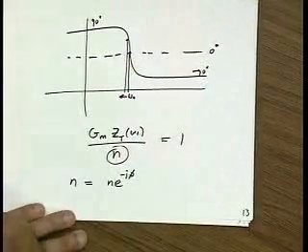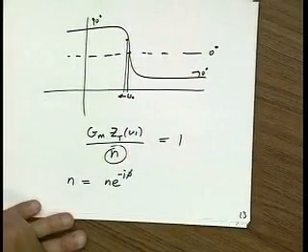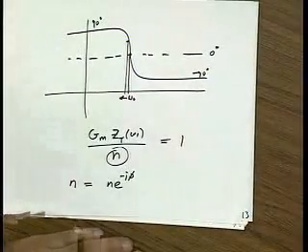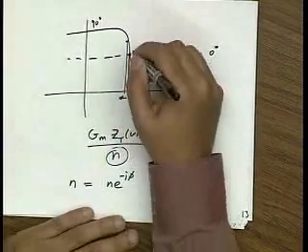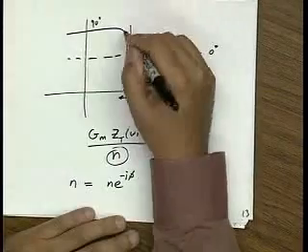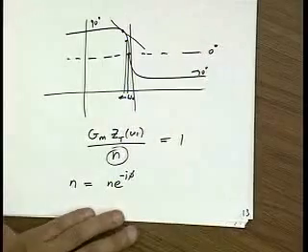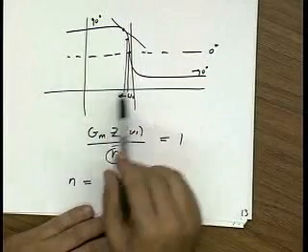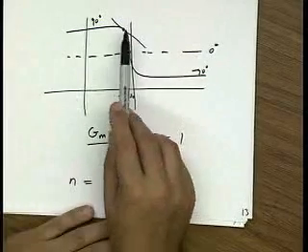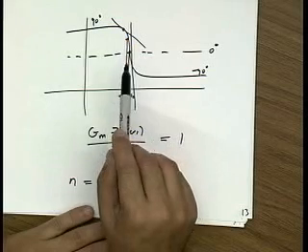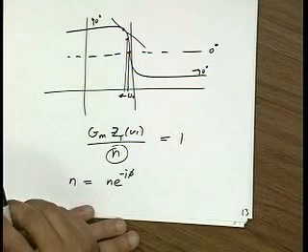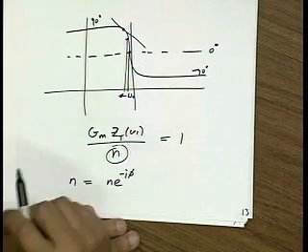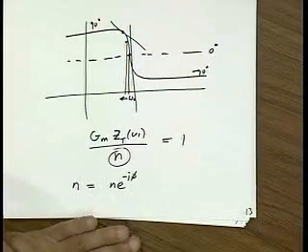So you might say, big deal. I'm not going to resonate exactly at omega naught. I can take that into account. Yeah, but you find out that the best point to oscillate is right here where the slope is maximum. You don't want to get to a point where this slope gets small, because the sensitivity of this circuit to phase noise is very much related to the slope. The higher the slope is, the less sensitive it is to noise on the phase. And so if you want the circuit to have good phase noise performance, you want to oscillate at omega naught.